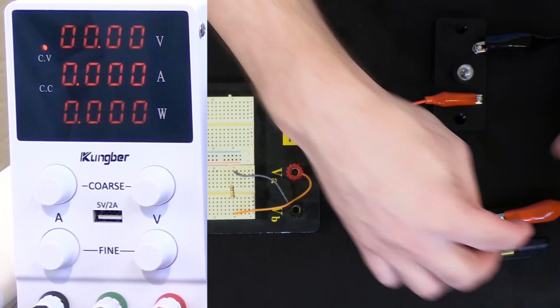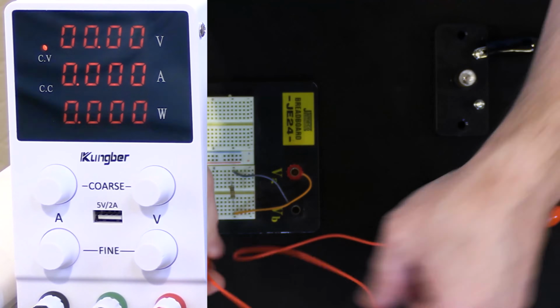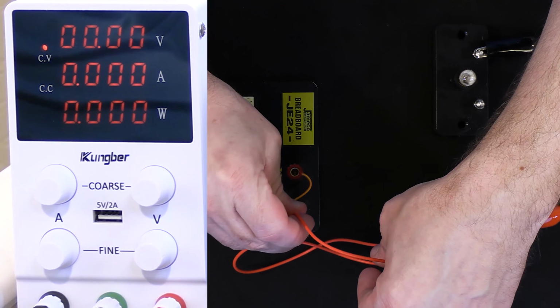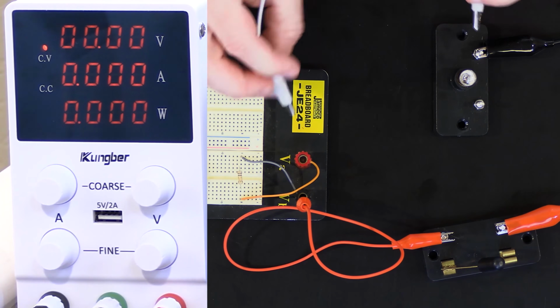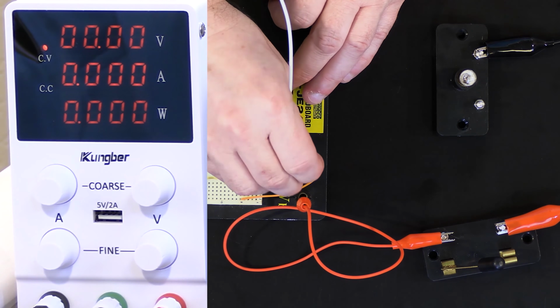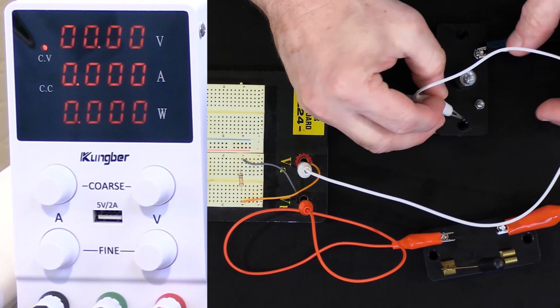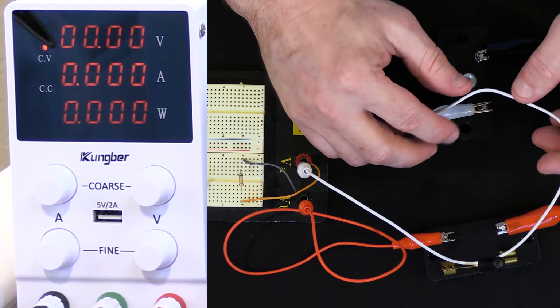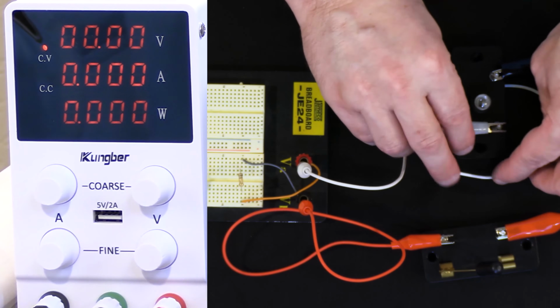So what I want to do is introduce this 1 ohm resistance into the circuit. How will I do that? First of all, let me open up the circuit so there's nothing going on there. Let me disconnect the light bulb from this one side, and I'm going to connect this to this side right here. I'm essentially opening up the circuit, but now I have to reclose the circuit again. And I'm going to show you how this little breadboard device works. We're going to use it a lot because it's very easy and helpful to build circuits rapidly, so you're not doing soldering or anything like this. So here we have, if I can get it to stay down here, that's pretty good. Something like this.